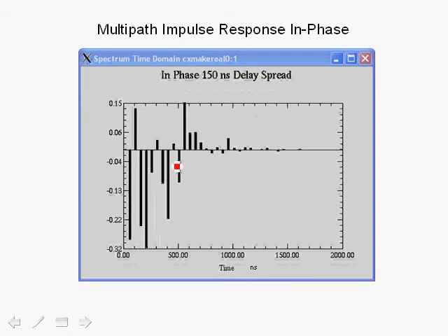If we go back to the impulse response itself, one way to model these impulses is that, due to the random nature of the environment and the multipath and scattering, each one of these impulses will behave across multiple realizations of the channel. They will exhibit a normal distribution, so that they are Gaussian. If you measured multiple impulses at a particular delay and measured the actual received signal at this point, and created a histogram of those impulses, they would exhibit a normal type distribution.